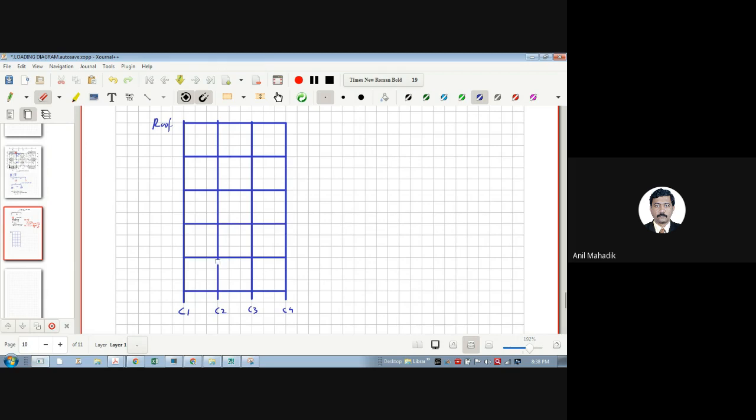So what we do in this case, I will remove this. So C2 is removed, but I have taken that C2 from here to above. Let me call it FC2 because it is now floating. So my FC2 is floating from this beam. This beam I call a transfer beam, TB. Now this beam will have more load here. FC2 will transfer the load from here to here.